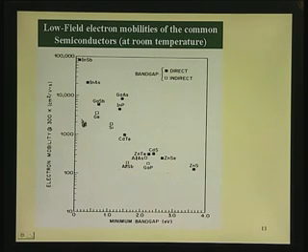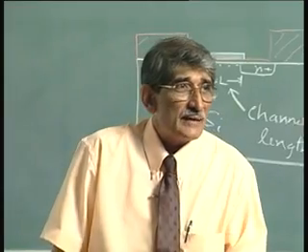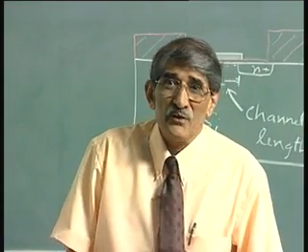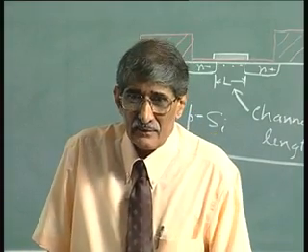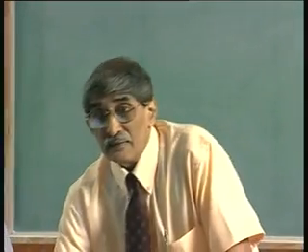So, any material which lies to the left of this vertical line, you cannot take, because to the left of that the band gap is small. You do not like to take any one of these materials, though the mobility is high. It so turns out that all those low band gap materials have very high mobility, but are no use for microelectronics. They may be useful for some other things, like detectors, IR detectors for example.